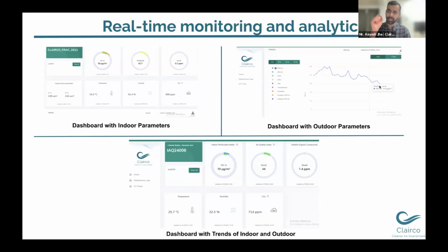But still, that small 2 to 4 Pascal of positive pressure can ensure that outdoor pollutants do not enter the building. Otherwise, it doesn't matter how good the air ventilation systems in your AHU levels are, the air quality will not be maintained if you don't have a positively pressurized building. And we've seen this in so many places across.